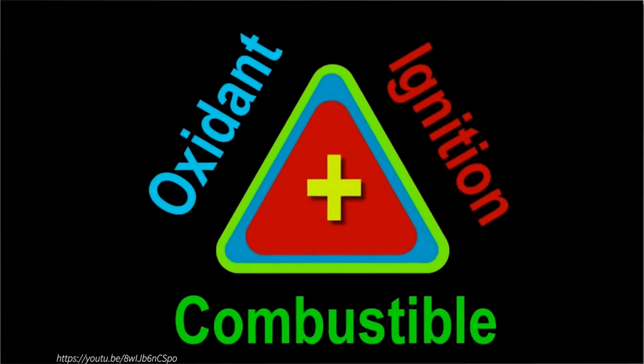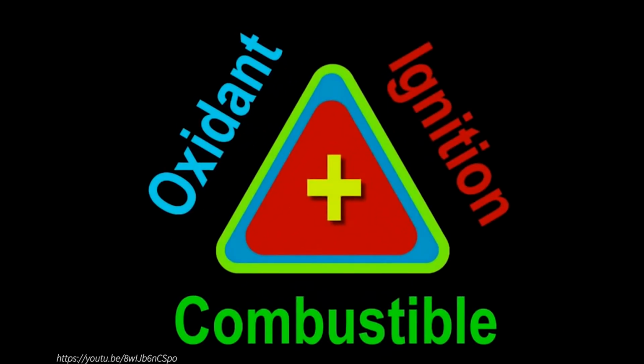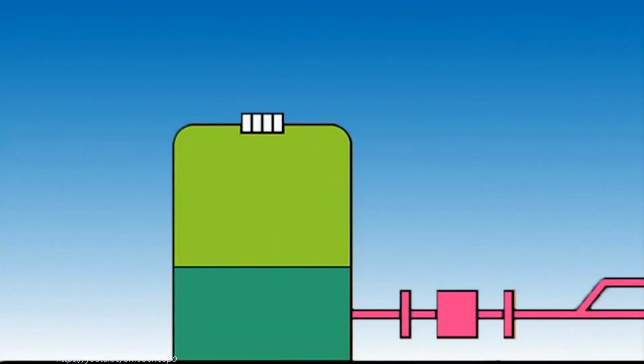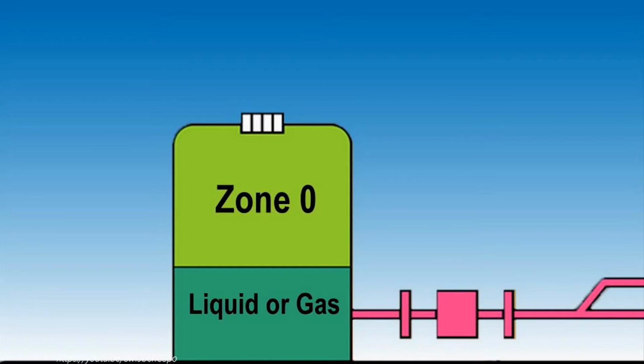Referring back to the necessary requirements for an explosive triangle, we know we need an ignition source, oxygen, gas, and/or dust combustible material in the correct mixture within the atmosphere. In order to specify electrical devices and hazardous locations, we need to identify the general zones within each area. When working with liquids or gas, we locate the most hazardous or flammable location directly above the material.